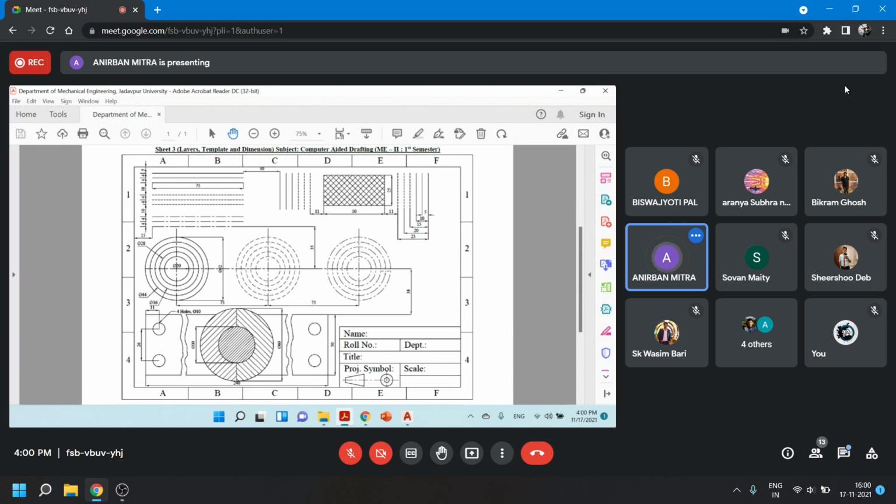So obviously you can guess that you have to create the different layers. You have thick lines over here, thin lines over here. These are probably thin lines with dashed line type. Center lines also have to be thinner than the object lines. Dimensions are provided for all of them, so you can very easily create these things. Hatching marks are also to be provided in certain components, right?